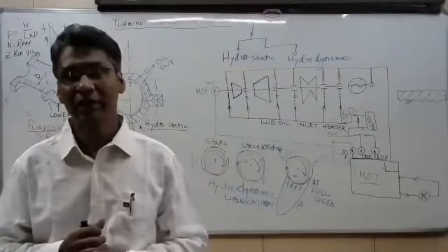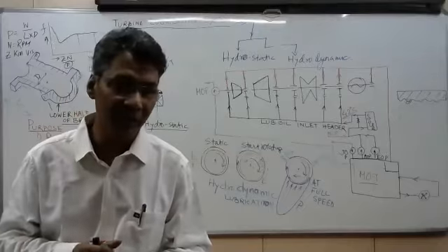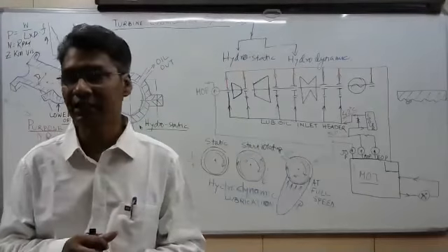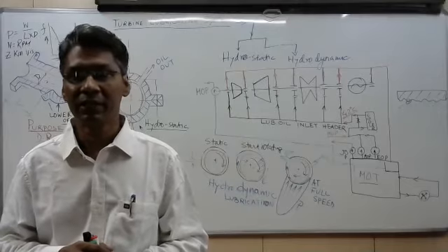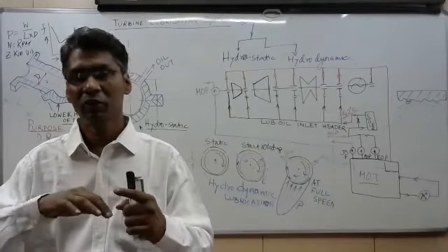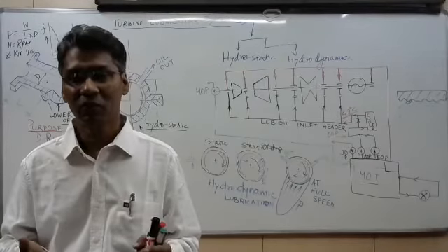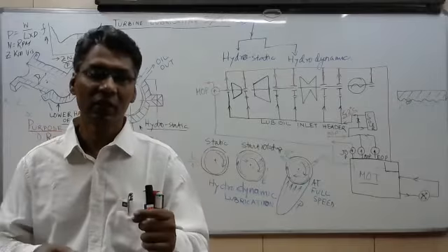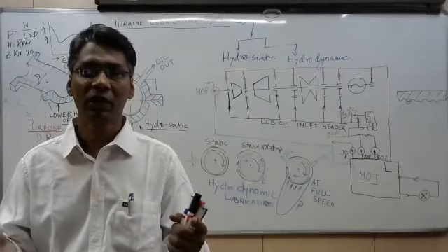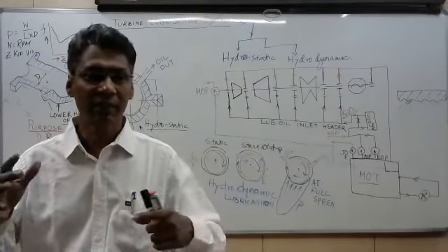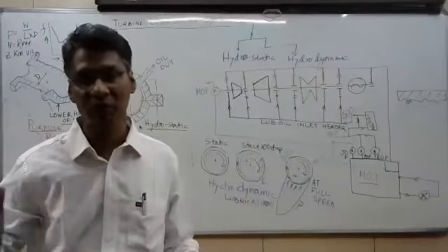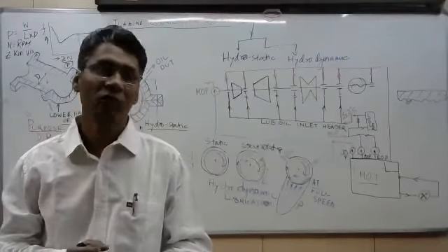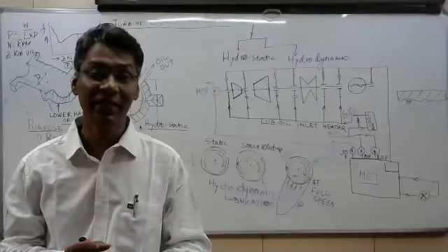So the hydrodynamic bearing is not developed today. It is an earlier developed one and research has been done. Once metal to metal contact takes place, suppose you don't provide oil, within minutes all the bearing will burn out and melt down. The turbine rotor will be damaged and the turbine may come out from the floor. That is a disaster that will happen. So that is the idea.